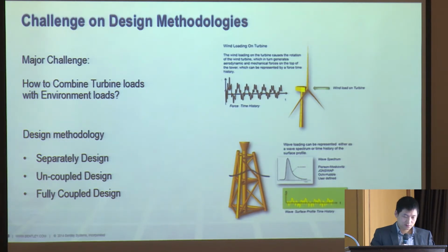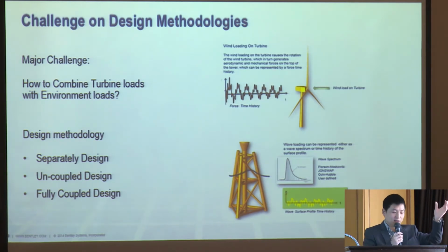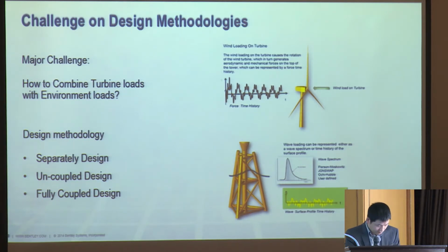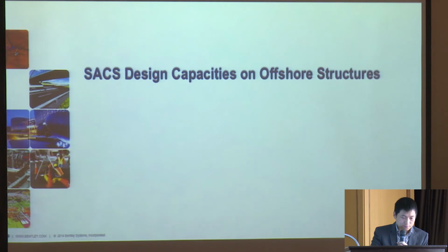The separately design means that we calculate environment loads in foundation structure design software like SACS, and calculate the turbine loads from Bladed or FAST, and then combine the loads manually. And the uncoupled and fully coupled design, we will introduce in the next few slides.